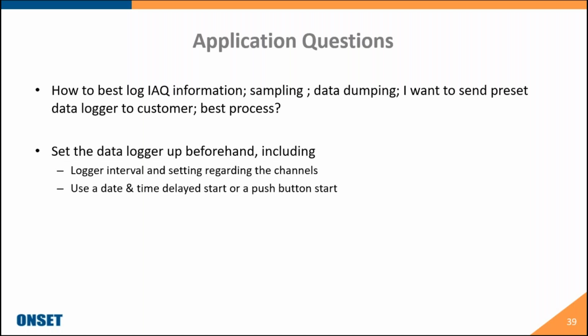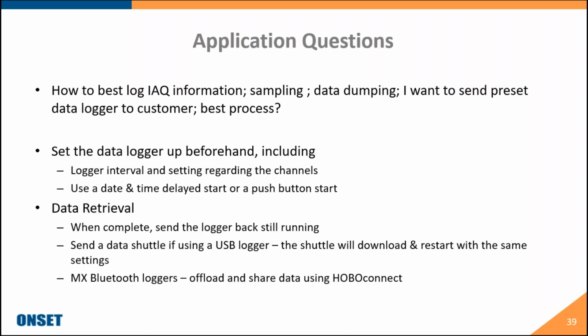Well, with our data loggers, you can actually go ahead and set them up beforehand by setting the logging interval and setting maybe any alarms per channel. And then you can also use our delayed time and date start and stop feature, or you do have the ability to set a push button start or push button stop with our USB and some of our Bluetooth data loggers.